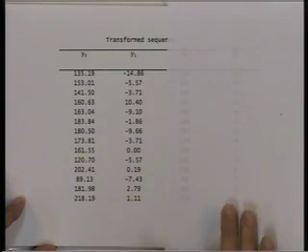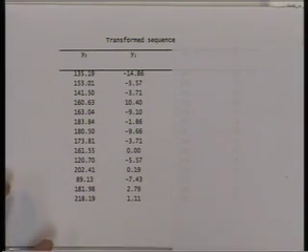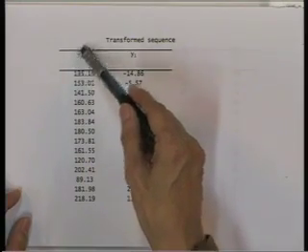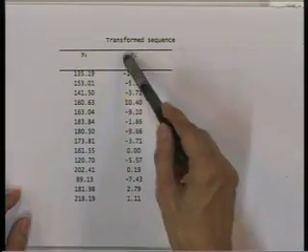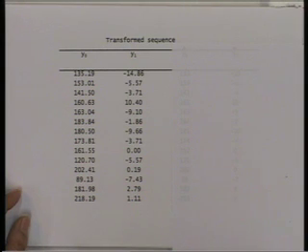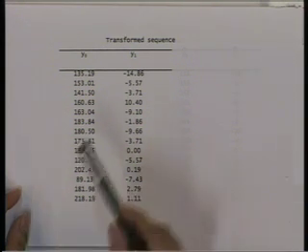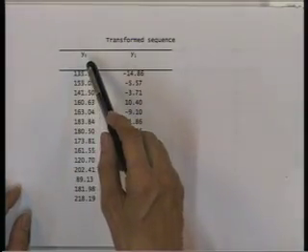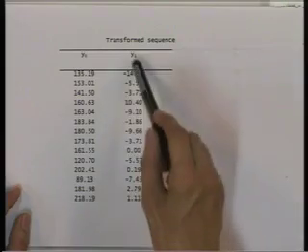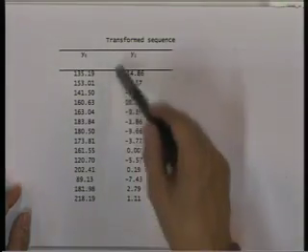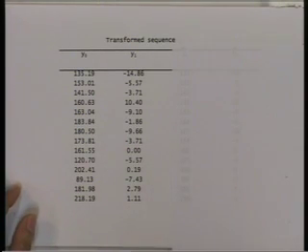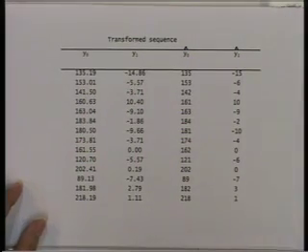Now, the next step in transform coding is to quantize these outputs y0 and y1. Let us assume that we use the same quantizer for both components y0 and y1. We use a uniform quantizer and quantize to the nearest integer. If we do that, we get the following result.